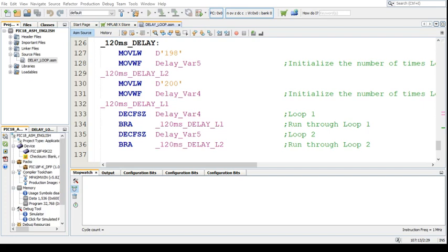In this case, I'm going to take 200. So you say 200 multiplied by 100 divided by 120, and that will give you a value of 166.67. If you replace the 200 with 167, you would get a time delay of 100 milliseconds. That's just for those of you that don't want to use the formula all the time.